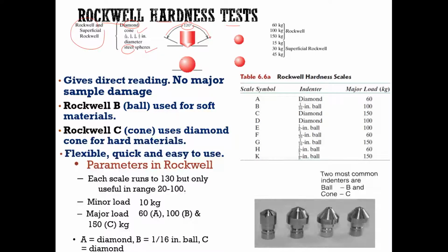And this cone also produces a circular indentation, right? So in your material here, we can see the circular indentation using this diamond cone. For a pyramid shape, you can see something like this, a square shape, right? This is the square shape for diamond pyramid. So Rockwell will only use conical shape and also sphere shape, and this sphere will also create a circular indentation.